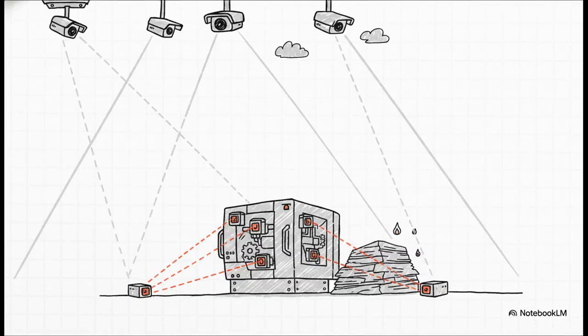Now, the reality for most modern industrial plants is that these aren't actually competing technologies at all. They are complementary layers. You should absolutely choose to use both when a fire event would be exceptionally expensive or dangerous to your operations. If you're processing combustible materials, or if you have high-value equipment sitting right next to a high fire load area, you want that belt and suspenders approach. You layer AI video for broad facility-wide smoke detection, and then you aim dedicated thermal cameras directly at your highest-risk assets for that localized heat-first monitoring.